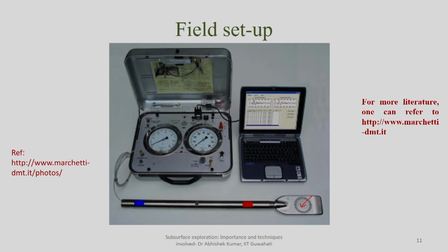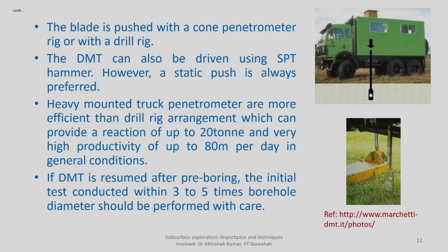You can see the dilatometer, which is connected to a drill rod here. You can use more drill rods as you go deeper and deeper. This is the pneumatic cable. Then there is another cable used for the electric connection, in order to ensure the buzzer circuit is complete, and this is the membrane. So this is a field setup.